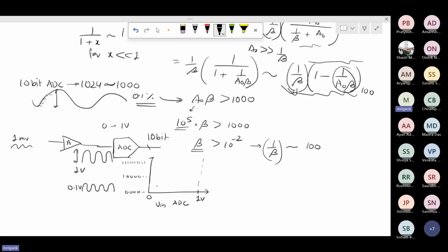So if you look at the ADC characteristic, it will be like a staircase function, a tiny staircase, linearly increasing, something like this, going all the way to the maximum. The way I have drawn is a little dirty, but it will be a straight line, a staircase kind of function, going all the way to 1 1 1 1 1 for input voltage equal to 1.